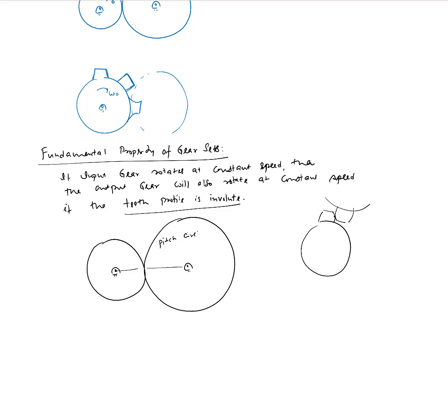So think of every gear reduced to a circle or a disc or a wheel having a radius equal to the pitch radius. So you have, let's say, radius r1 here, radius r2 over here. Now once we idealize gears as two circles rolling on top of each other, the analysis becomes very, very simple. The analysis would proceed along similar lines as we did for the pulleys.